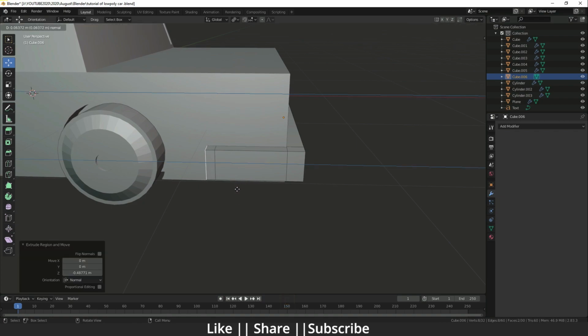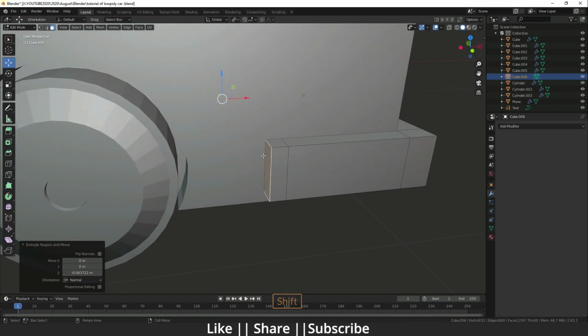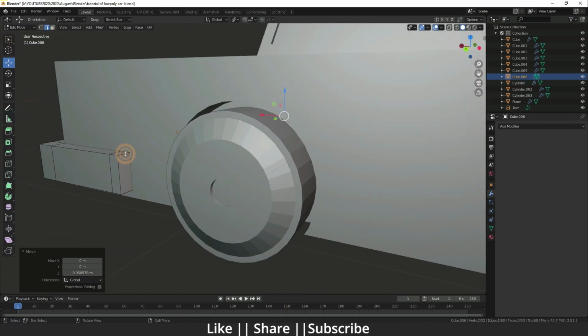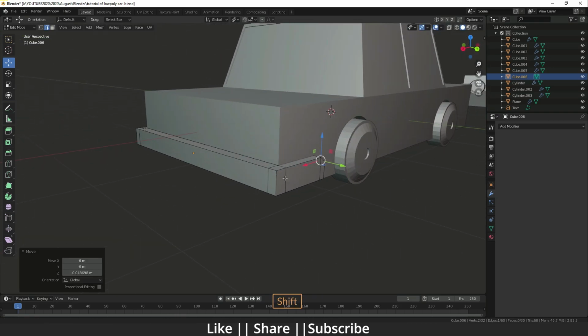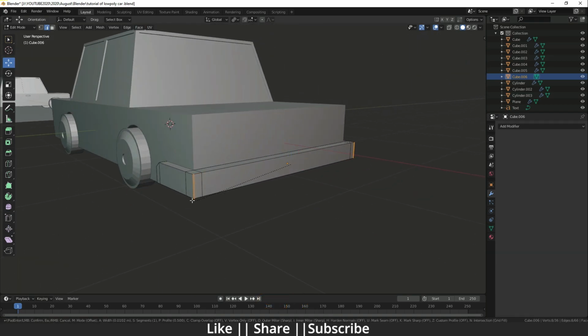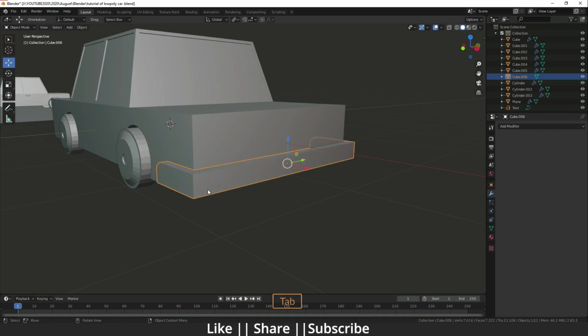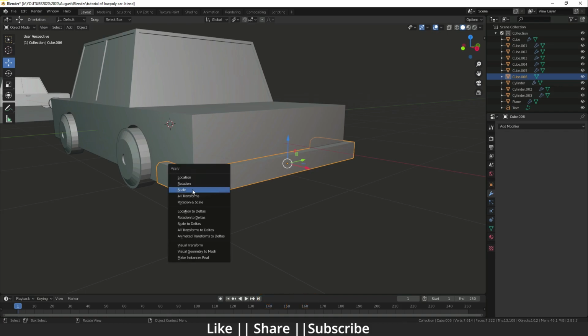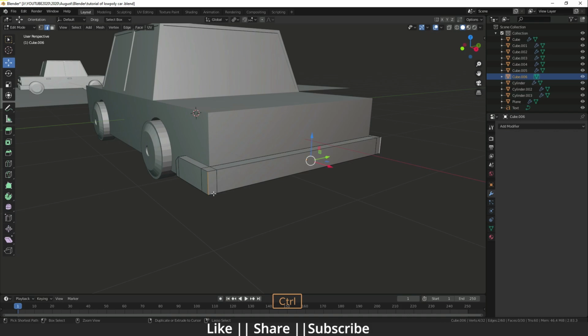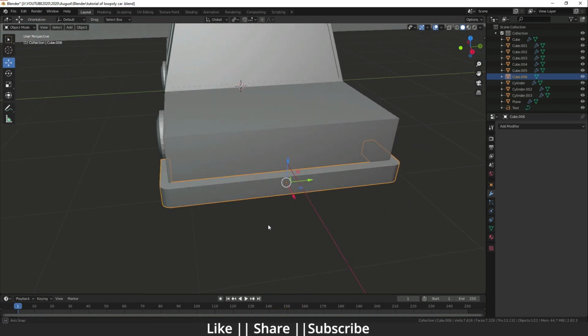Okay, and I'm doing extrude once again, and now I'm just going to select that edge and do like that, and like that. Okay, and I'm just going to bevel both faces like that. But when you do the bevel, you can see that the bevel is not working properly, so we have to do the same thing here. Just exit the edit mode, press Ctrl A and apply the scale, and after that when I do the bevel, my edge is perfectly beveled. So now it's looking cool.